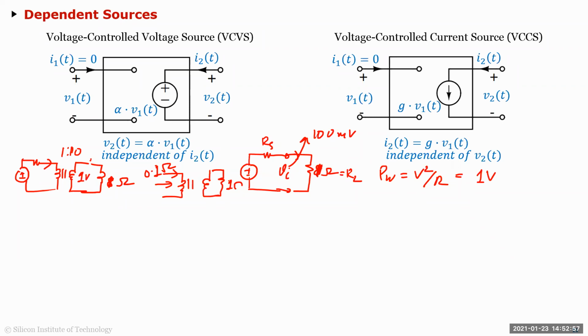So that's why you need a voltage controlled current source. What that does is you can supply some voltage and the output is independent of the load, right? So the output will drive the load. So now if I have a transconductance here, so I have a transconductance. Let's say I'll draw the four port model here, and this is 1 ohm.